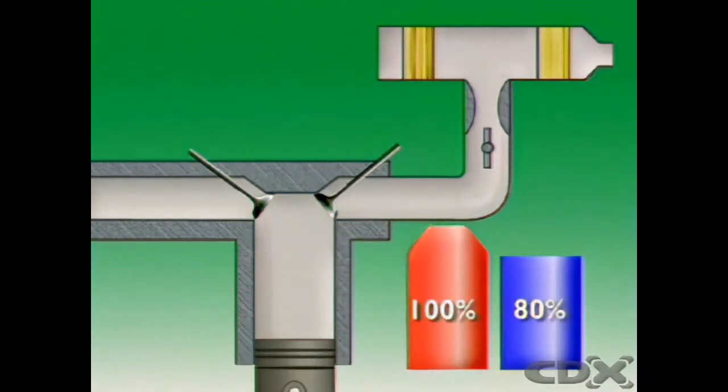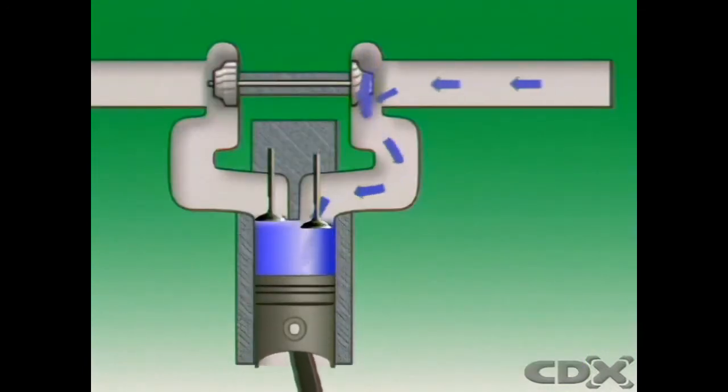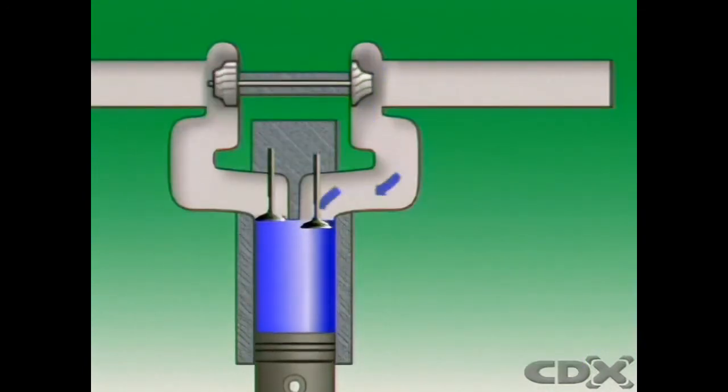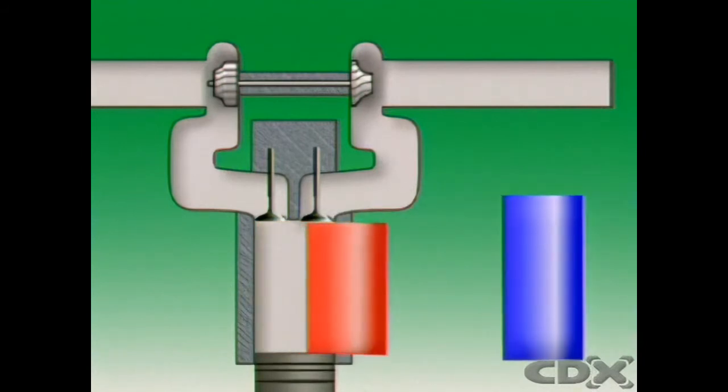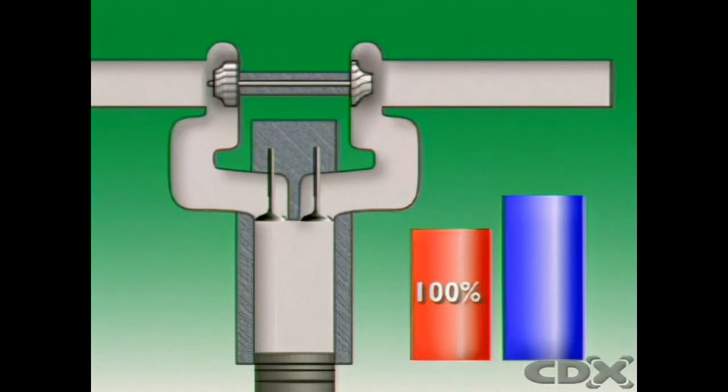This is because of the resistance to the airflow that occurs at the carburetor, manifold, and the intake valve. With forced induction, the incoming air is compressed so that a greater volume and mass of air is forced into the cylinder during the intake stroke. That takes the volumetric efficiency to above 100%.